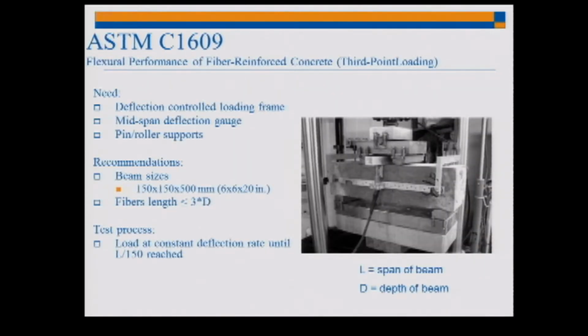So one thing is how do we figure out what fiber to use, how much fiber we want to put in, and a bunch of people have come up with this standard as kind of a reasonable way of testing a fiber reinforced beam. It's a standard beam actually, but we have to measure the load displacement of this beam and measure that after the peak load also. And this gives us an idea of the toughness of the fiber, or of the fibrous concrete. And we can then look at the quality of the fiber.